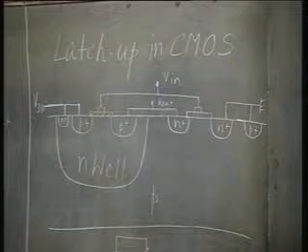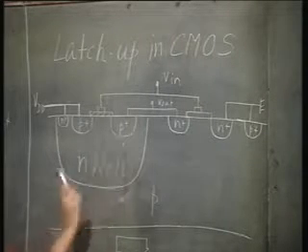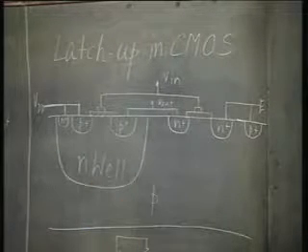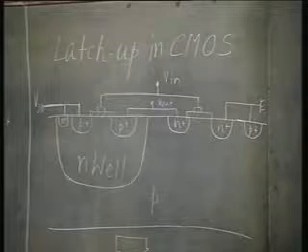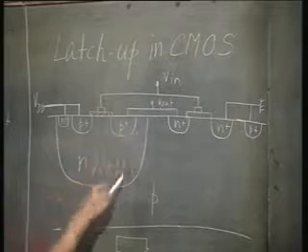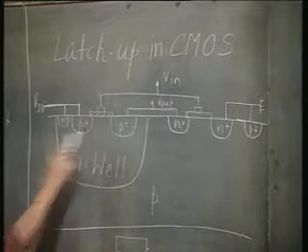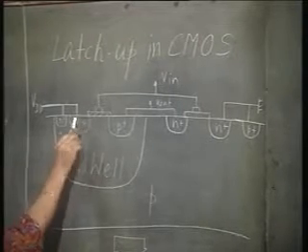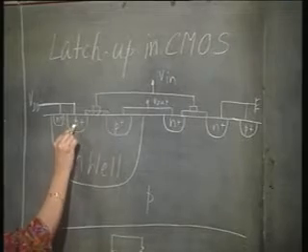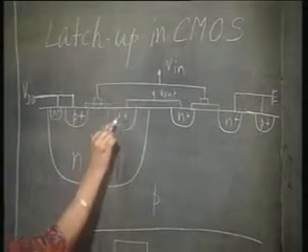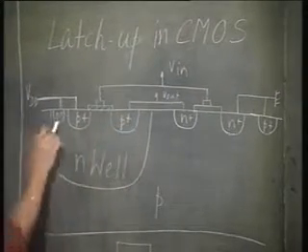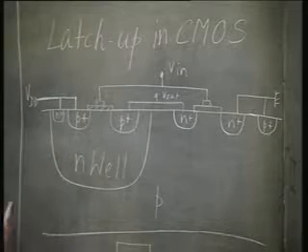Let us look at this circuit. I have the N-well here and the P substrate, right. So, the substrate doping is very low. In that I have an N-well. Inside the N-well my PMOS is housed, right. This is the P source and drain, P channel source and drain, and I have a substrate contact.